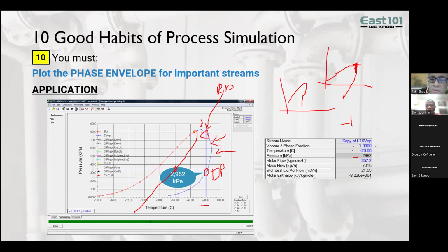So if your system exhibits this retrograde behavior in HYSYS or Unisim, if you punch in 1, you see this, a blue 1 and a blue minus 20, it will calculate the dew point pressure for you. If you punched in minus 1 into this case, you would get 8,000.